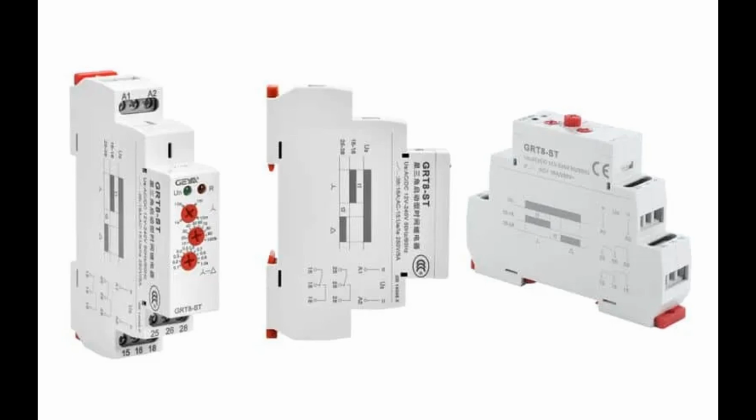Resistive load rating. Resistive loads, such as heaters and incandescent lights, typically have a steady-state current draw without significant inrush or back EMF. Time delay relays rated for resistive loads may have lower current ratings compared to relays intended for inductive loads, as they do not need to withstand the same arcing and transient conditions.